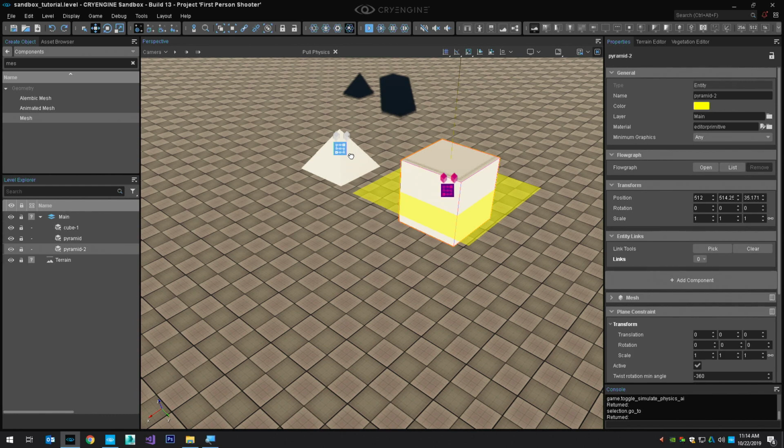As we get closer and closer to 0, in a calculation curve like this, those numbers get smaller and smaller and smaller, and we're approaching infinity. And those calculations become pointless and meaningless. So how we get around that is introduce artificial damping, which says, I'm going to put the brakes on. It's just brakes. So I suggest that you do introduce some kind of damping force so that things don't move forever, unless they're guaranteed to collide with something.